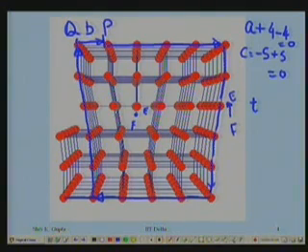The direction orientation of the Burgers circuit should be such that the right hand screw goes in the direction of the dislocation line. Right hand screw will go from F to E if I go clockwise. If I go anti-clockwise, it will come from E to F.